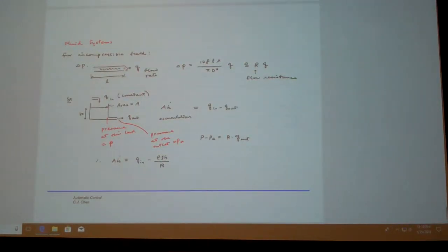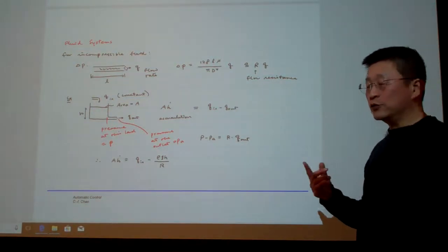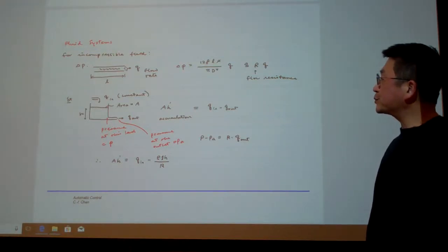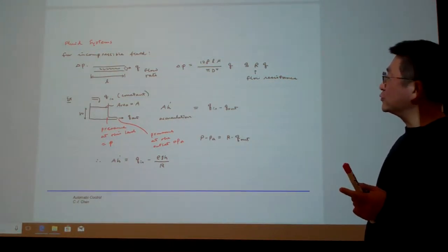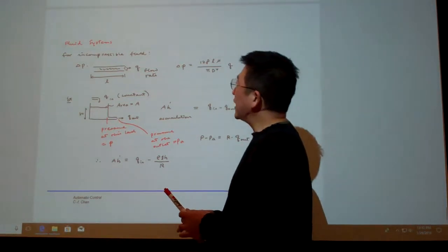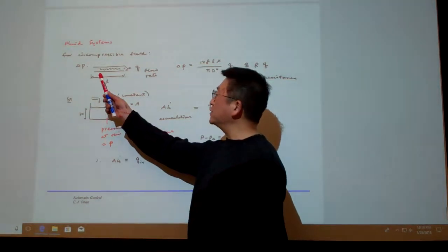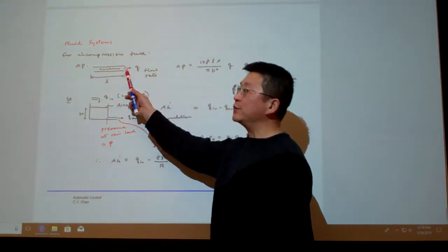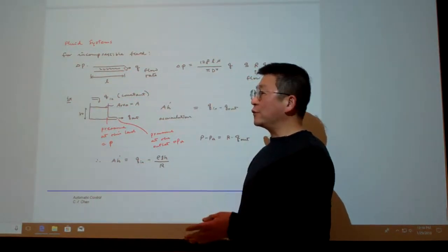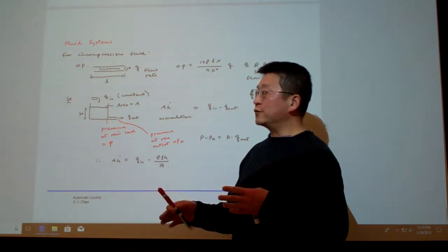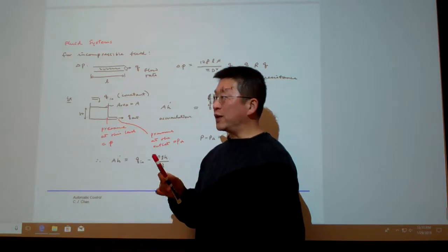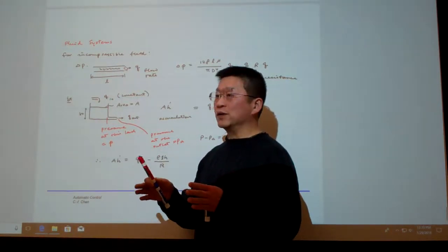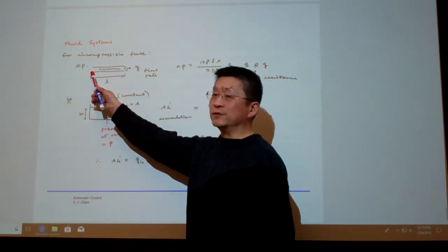Now this one is the fluid mechanical fluid system, and only one page. I will do it very quickly, and basically only pretty much one rule is this. If you like to have a viscous fluid to flow through a pipe, if you want to have a flow rate, which means equivalent to the electrons, if you want to have a fluid to flow, then you must produce the pressure drop, or they call the pressure head, at the upstream, right?